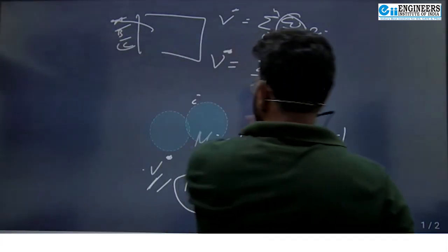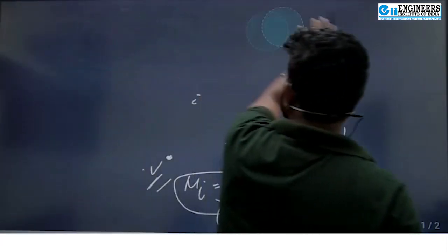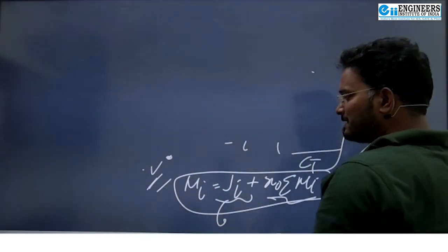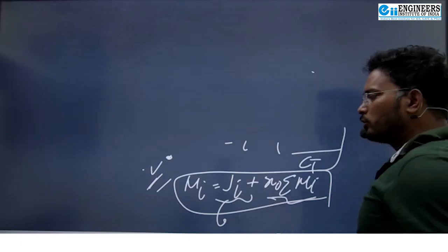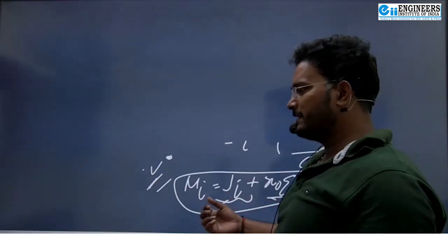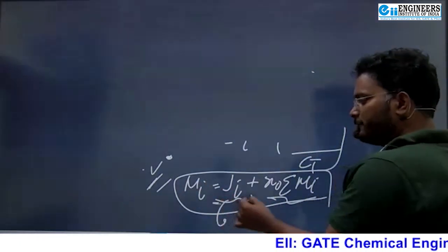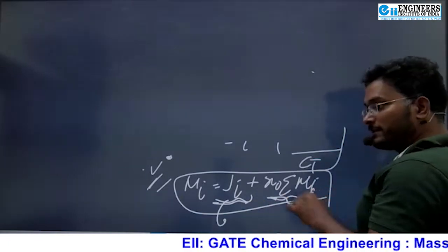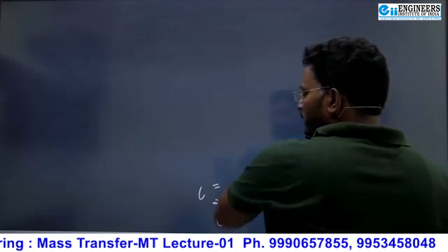This is actually, my dear students, in this case we have not considered any reaction. So you will see two terms ahead, but that is very important: that is in the same direction, no? The two contributions are there, Ni, the flux of species i in a given direction. So it is a diffusive flux in the same direction and bulk flow in the same direction. Okay.